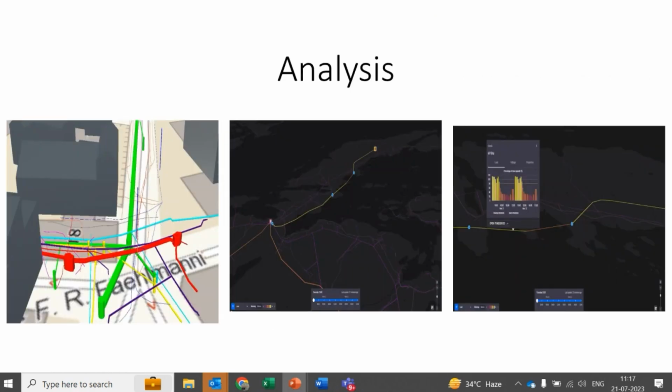And then you can do different levels of analysis on top of that. You can integrate it with the SCADA system for real-time operations, for pressure, flows, flow directions, for pumping stations, for energy that is used in the pumping stations.